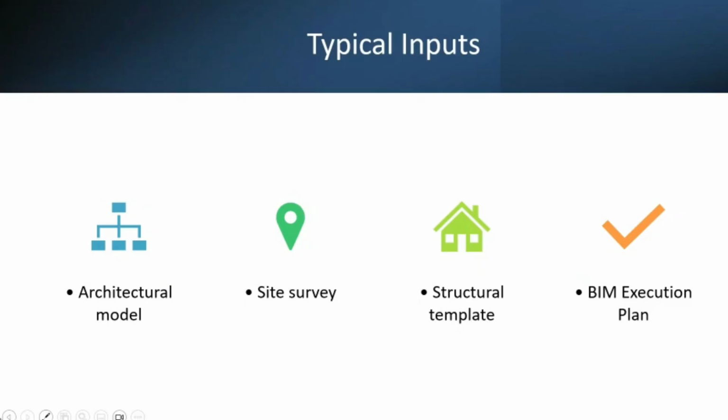So they prepare contour lines for all the site, and based on real-world coordinates, you need to link that site model and position your model in real-world coordinates.